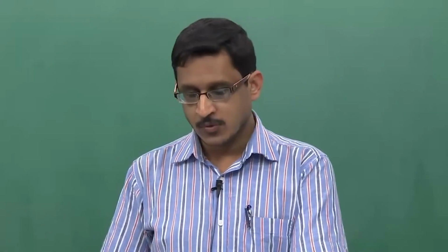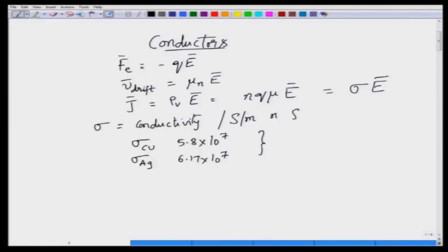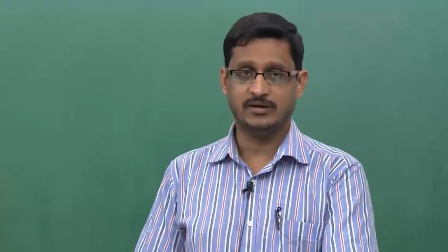transmission lines. Moreover, the conductivities that we have given the values for are not really constants. They are dependent on temperature, and for every 1 Kelvin rise in temperature, the conductivities would actually change by about 0.4%. In fact, this can be used as a very sensitive temperature measurement instrument. Now, let us develop one very important relationship between the voltage and the current of a conductor.